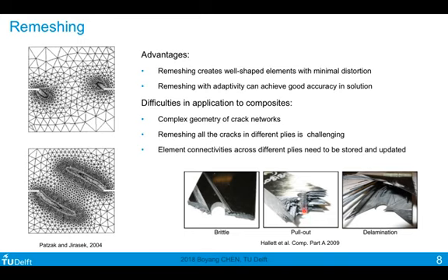In the case of composites, you could have hundreds of matrix cracks, and you have many plies also. Together with delamination, it is then not very practical to apply remeshing there. Now, we need to come up with more efficient and also effective ways to model crack propagations within materials such as composites, and the crack propagations need to be independent of the mesh construction.